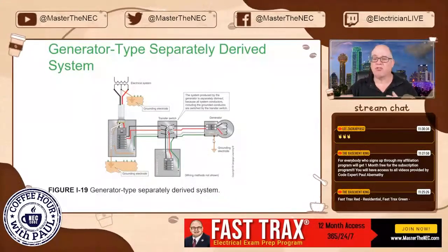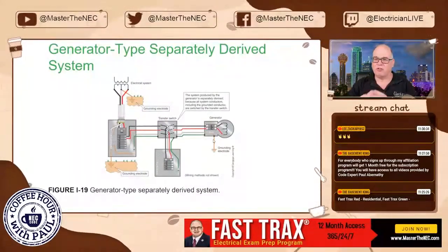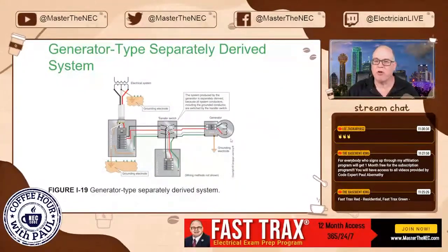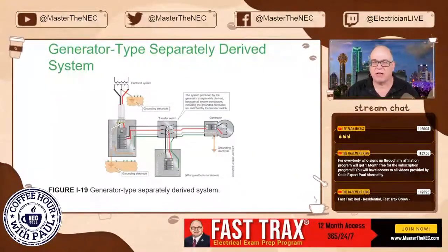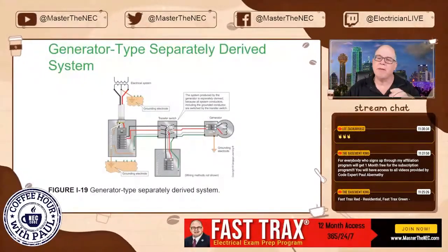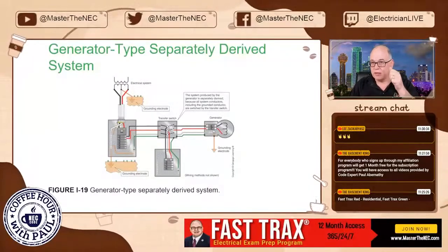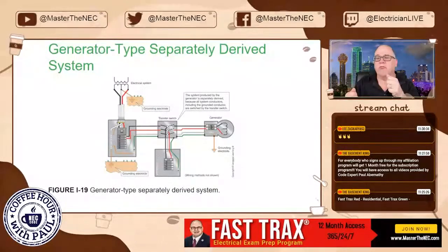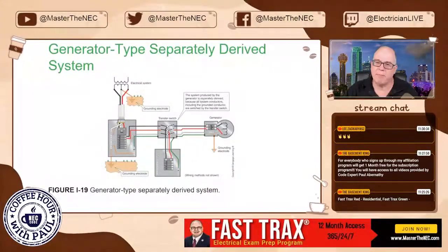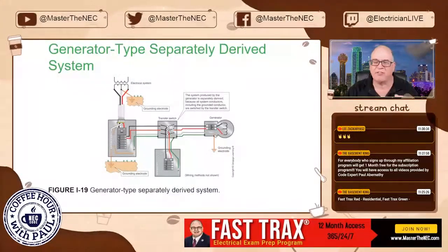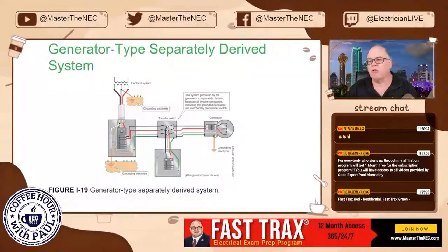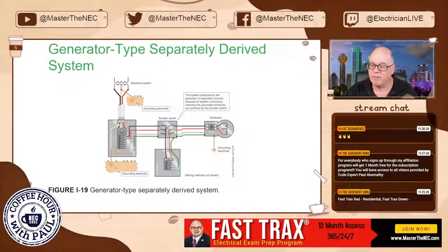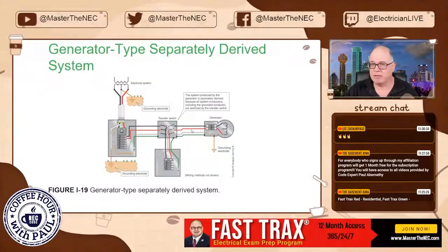So make sure, as an electrician, if you're installing a generator, that before you connect any of the conductors going out to it, the feeders going out to it, you check between the grounded point and the case and make sure it doesn't ring out. That's before you get any back feeding through these conductors. Just check it first and make sure you don't have a system bonding jumper installed if it's not separately derived.